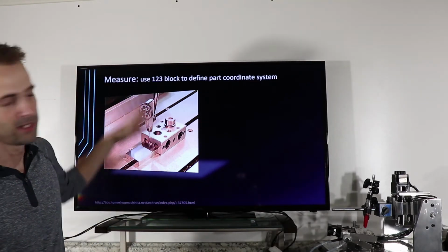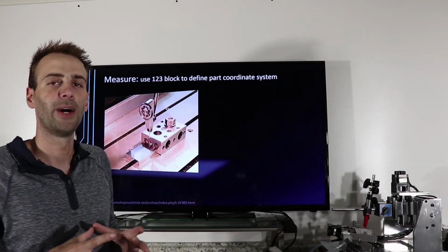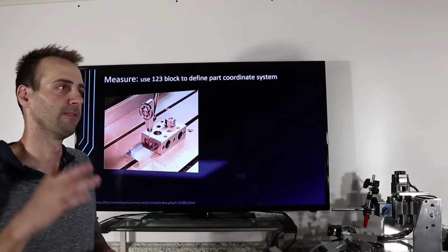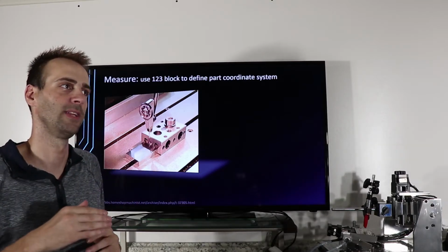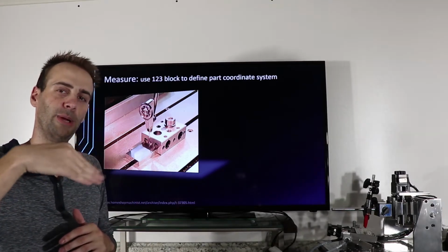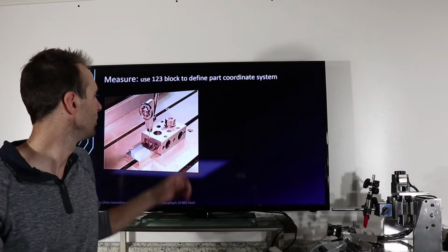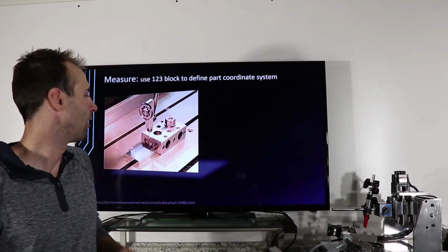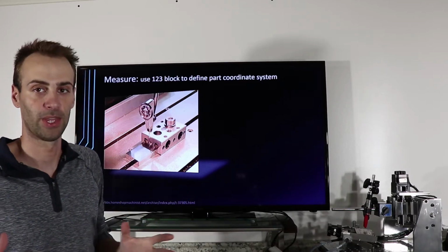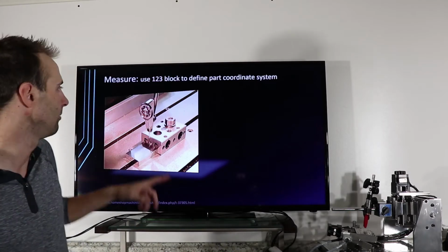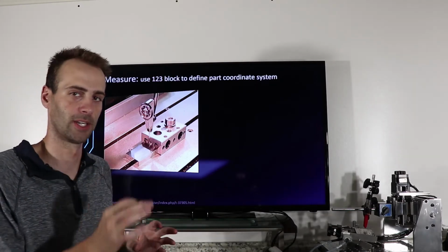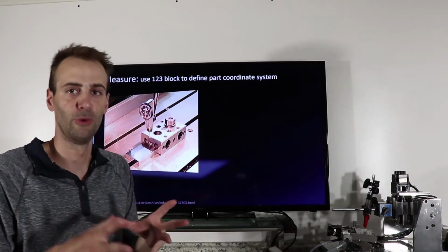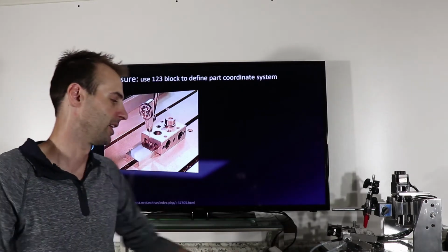So, our measurement utensil for the DIY community is almost certainly going to be a dial gauge, and this one is the sensitive type that has the feeler on a pendulum type of thing, and you can get these that read in tenths. I think even at Harbor Freight you can get ones that read in half thousandths, and these just tend to be a little bit more sensitive than the plunger type dial indicator. But in either case, let's just assume that this is going to be the setup to characterize a machine.